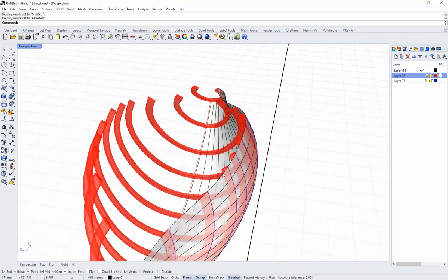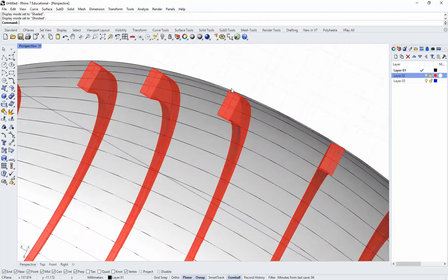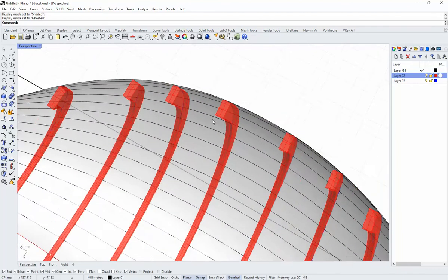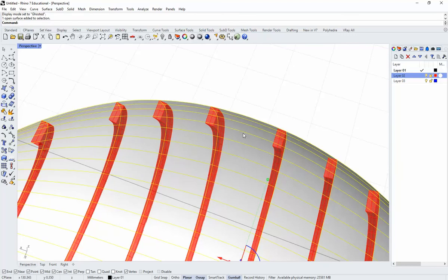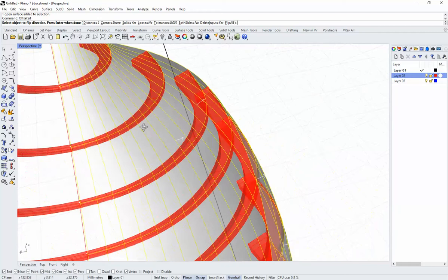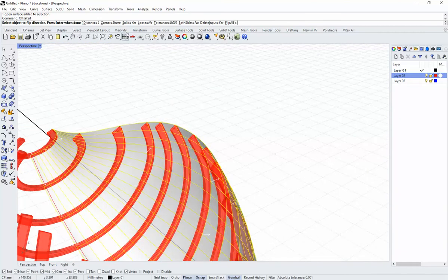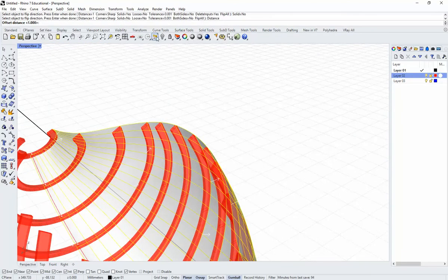What I would do in this case is just offset the surface ever so slightly so that we get a little bit of breathing room there. And I think the drawing line weights would make up for the rest. It'll fill that gap and it should be nice and accurate. Again, any super detailed drawing that shows the connections is going to need to be redrafted anyhow. So this is really just a way for you to get a structure for that drawing going. Let's offset that surface, make sure it's going outward. It is. Solid no, distance is going to be something very small.